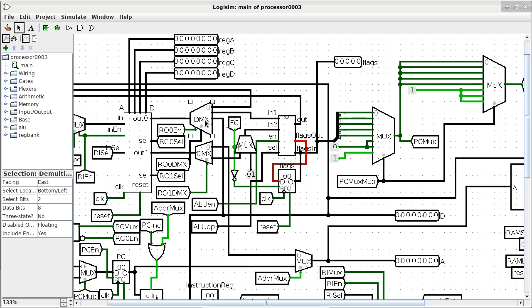It has one input, one incoming line, multiple outgoing lines, and then there's a select line to basically say which one of the incoming lines is connected to the one single outgoing line. It is directional. Unlike on a train track where things are not directional, when you're talking about electrical circuits, most things are directional. So a demultiplexer has one input and multiple outputs, and then the multiplexer has multiple inputs and one single output. That's the only difference.